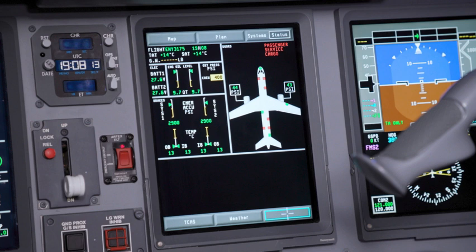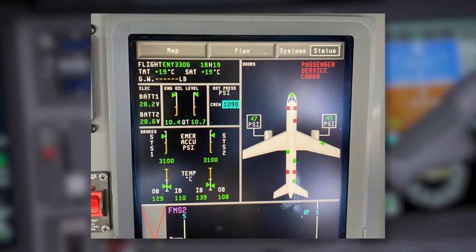During first officer's flight deck preparation flow, if the oxygen quantity displayed in the MFD status page is amber or cyan, when the ACM will be present, crew must contact MOC to service the oxygen pressure. If the oxygen pressure indicates cyan and oxygen cannot be serviced, flight deck jump seat must be MEL'd.